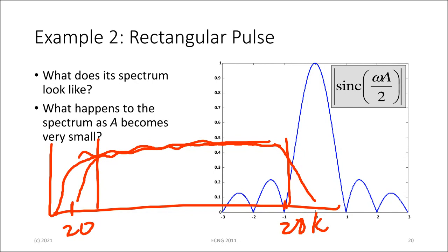would send, I mean, the traditional way you would do it would have been to hook up the speaker to an amplifier and hook a signal generator to the amplifier. So you start with low frequency, you put in a signal at 10 hertz, and you have a microphone measuring the output of the speaker. You put in 20 hertz, you measure the output, and so you go for the entire range until you pass 20 kilohertz, and then you plot out the response and see what you get.